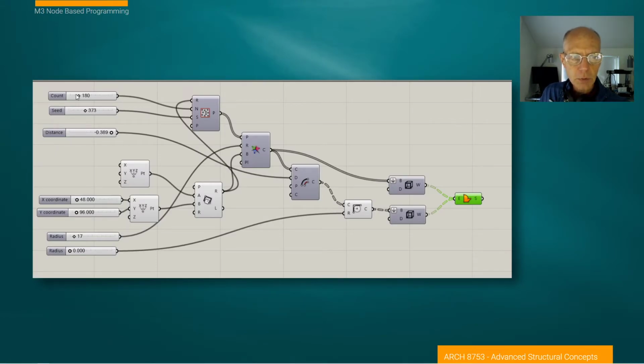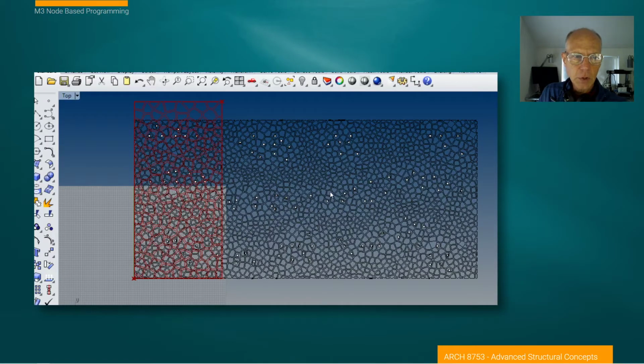And so I was able to use a really simple mathematical description using random seeding, creating a Voronoi pattern. This is a mathematical relationship about how we draw bisecting lines between points. I could offset those points to create the kind of gridded system we want. And I had all the adjustments to vary the number of panels, how thick that offset would be, the size of the panels, the amount of randomness that I wanted to introduce, the curves where the points intersected, all with a simple definition that led to an output file that looked like this.